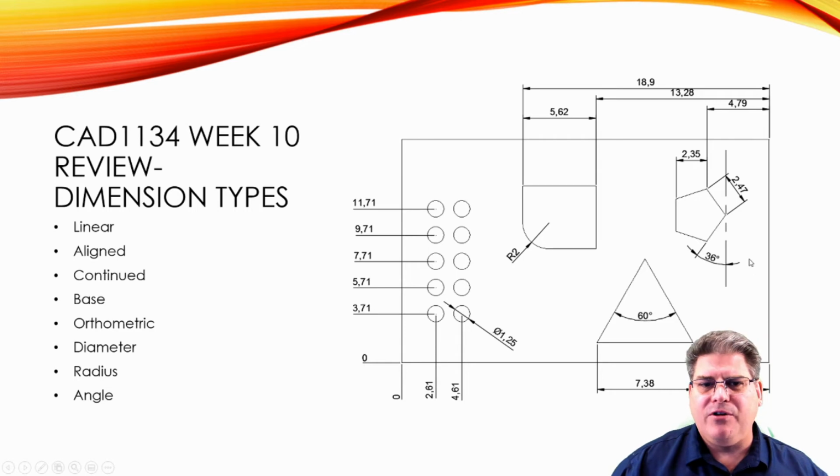It's more clear than trying to call this dimension from here over to this edge. I mean, you could, but this also could be a theoretical line between this hole and this hole. Nothing says that it has to be relevant to any other geometry either. It should be, but radius and diameter, definitely two things that can be placed with any dimensioning style. So feel free with that.